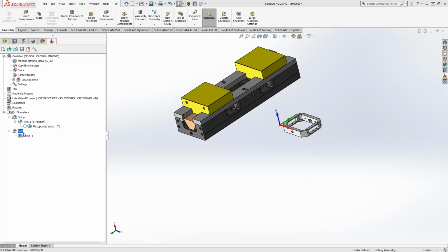If you guys have 2 setups in there and it's not producing out into 2 separate G code files, then you can add that split in there too. Yeah, there's a lot of extra functionality in the post now. This is kind of an older way to do it, but I find a lot of our customers either don't do this or they don't think about this aspect when they do multiple setups. So I usually show the split, and if the split's not necessary, then you just eliminate it.